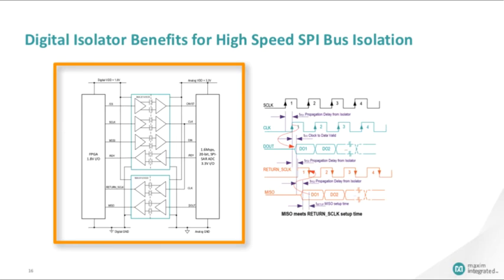At the input to the ADC, the isolated SCLK is represented as CLK and the isolated MOSI is represented as DIN. This arrangement is only possible if propagation delays introduced by the isolator and the skew between the respective channels of the isolator are both extremely small.